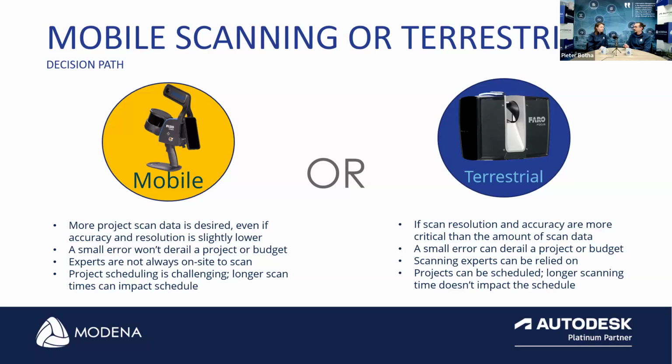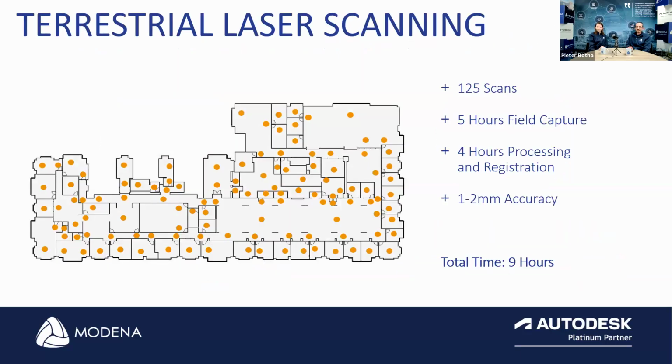Where you need the directional scanner would be more detail on certain objects, a lot more clarity on the site of the scan. It provides us with great image quality as well that can be used for measurements and so forth. And also the smaller area that you need, less tolerances for your scan size. So if you're looking for millimeter accuracy, the Focus scanner would be there for you. If you don't need millimeter but still fall within 10 millimeters, then the Orbis scanner would be perfect for that application as well.